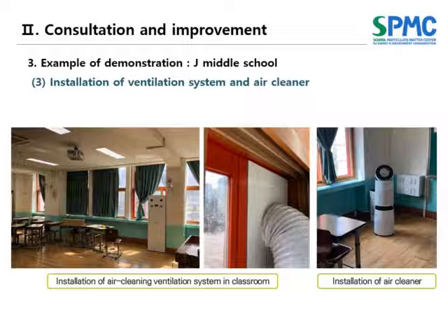This picture shows a stand-type ventilation system and air cleaner installed in the classroom. After collecting opinions from the school, we installed a stand-type ventilation system that does not require a ceiling diffuser. In addition, a ventilation system combined with an air cleaner function was installed to prepare for high outdoor particle concentration.